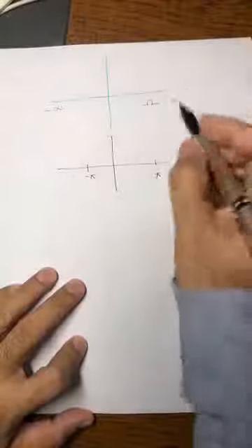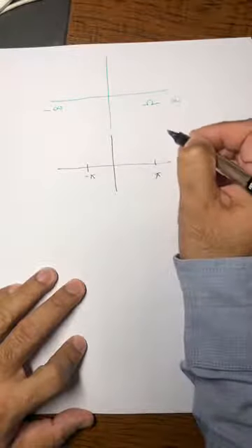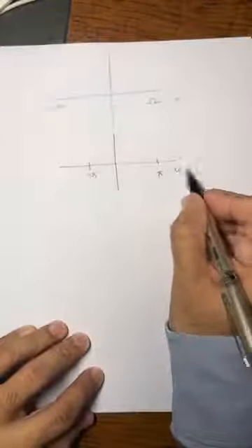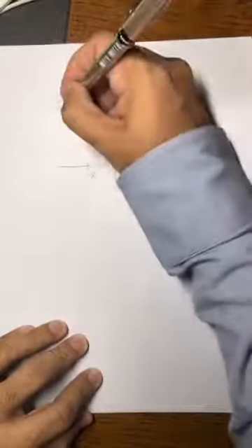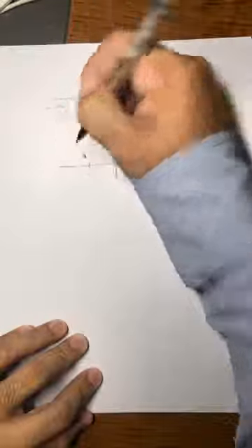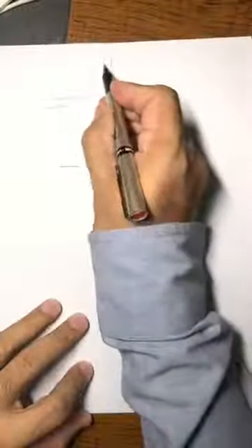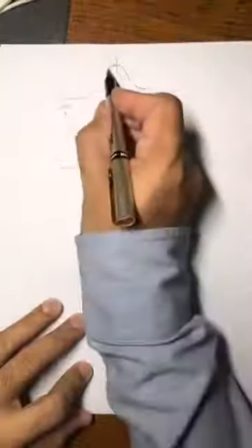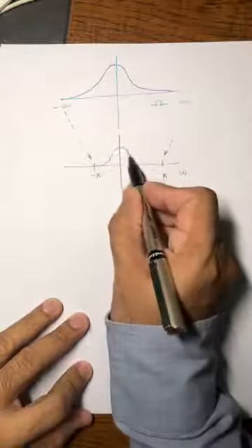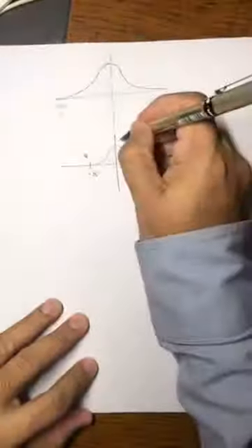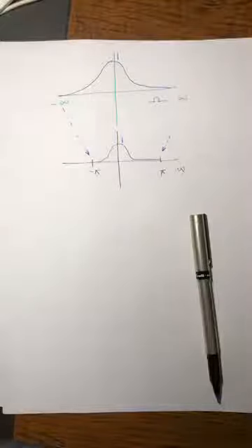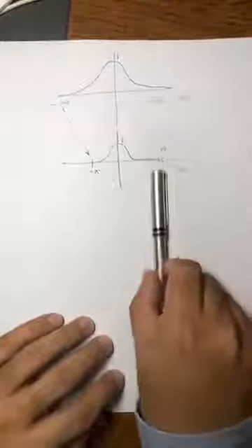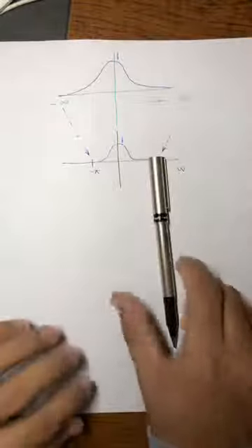The other obviously is, is it possible to somehow compress the whole frequency axis once you are converting it, and map infinity to pi, and compress this frequency axis and map this to minus pi, and the rest of this, for example, if it looks like this, it looks like that. Okay, so you have compressed it, without changing the amplitude axis, which remains as it is. So you compress it from both sides, and you make this whole thing fit into pi and minus pi,